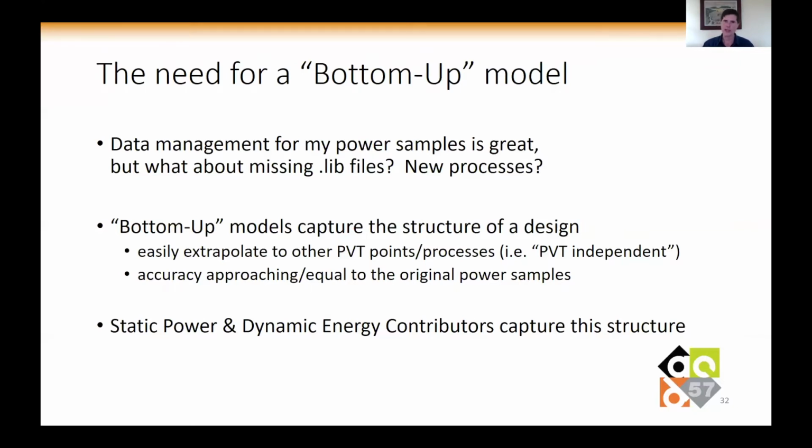So now, to be the most useful, I want to replace my top-down model with this bottom-up model, which means I need it to be equally accurate to the top-down model. And I can accomplish this by capturing the structure of the design using these static and dynamic contributors that Nagu mentioned earlier. So he introduced them, but let me take now some time to go into a bit more detail about each one, starting with the static power contributors.